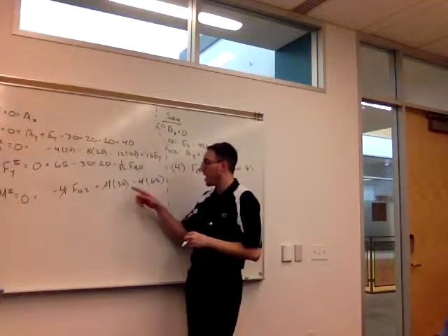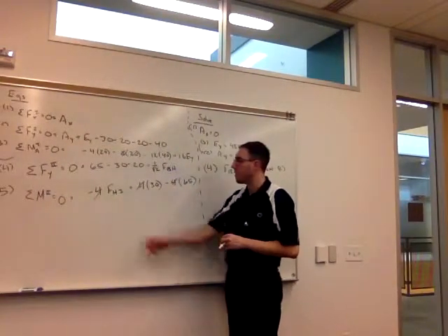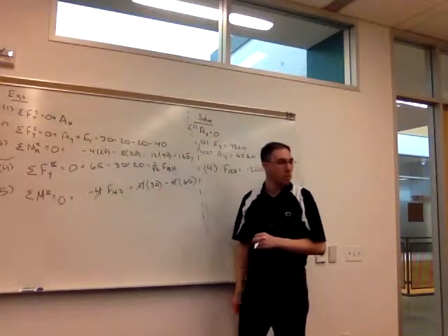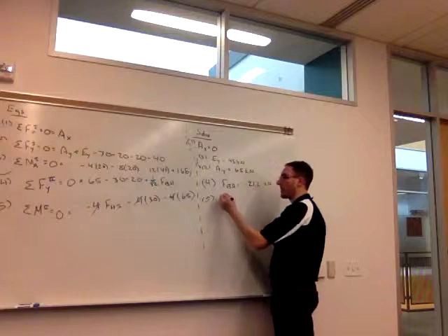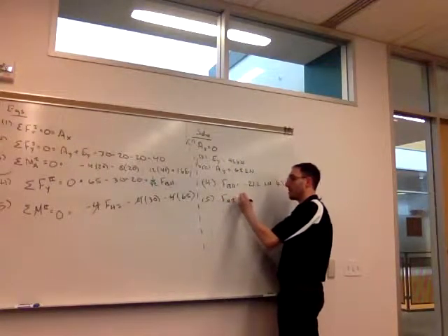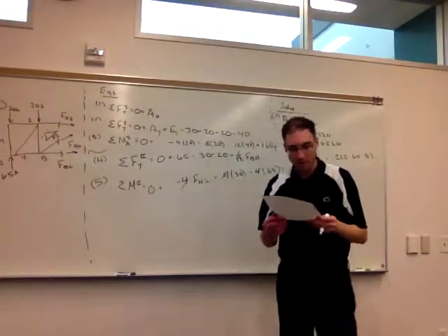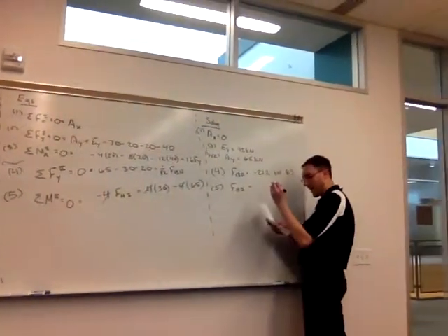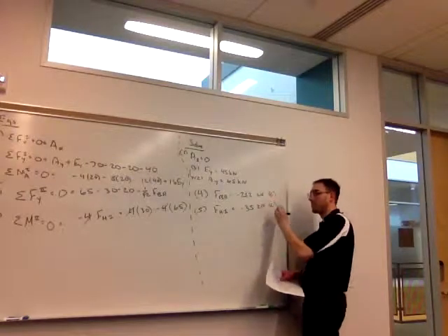Right, so from AY, the applied load of 30, and then FHI all contribute to the moment. I can cancel out that 4 to make it just a little bit simpler, but equation 5, now I can find FHI since it was my only unknown. So FHI, I get a negative 35 kilonewtons, also in compression.